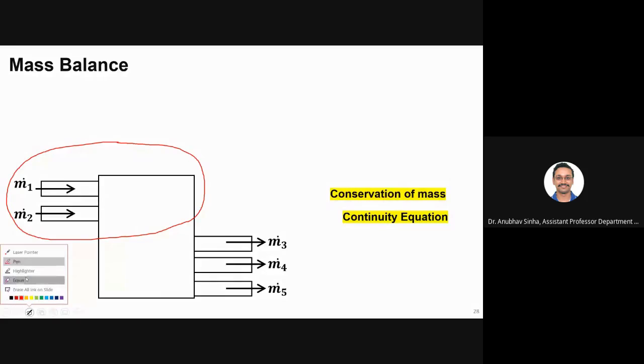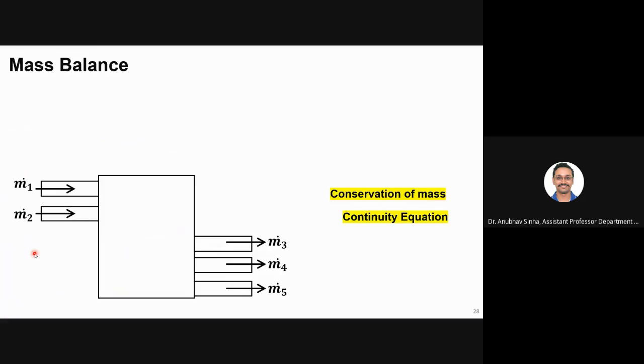Understand the difference? It is not that this is not allowed. The problem is that it will make your analysis difficult. So the easiest and most convenient way to define the control volume would be this: we take the volume of this tank as the control volume. But there is no rule or law which says that this must be your control volume. I can take even half of this volume and call it my control volume, but it will not be convenient. It will not be easy to work out numericals. Is this clear to everyone? Yes, sir.